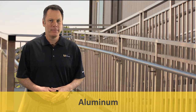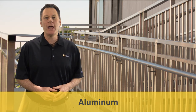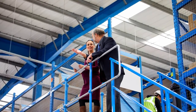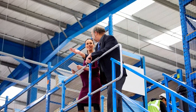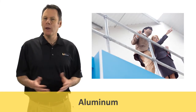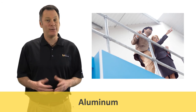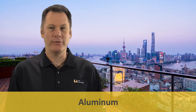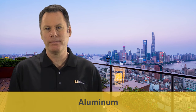Aluminum. Aluminum is a non-ferrous metal that is lightweight, strong, and known for its resistance to corrosion. Aluminum railings can be powder-coated or anodized to meet the aesthetic requirements of a project, and over the long term require relatively little maintenance. As a railing material, aluminum offers ease of fabrication and versatility in design and installation. Aluminum is used in outdoor applications such as decks and hotel balconies since it is resistant to corrosion.